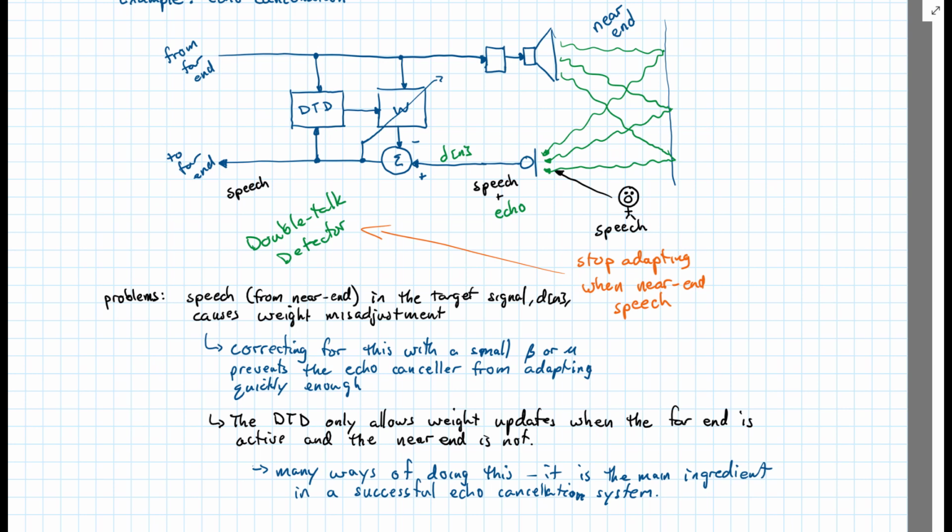So your filter is already starting to get longer, which of course slows down the adaptation. We can do frequency domain adaptation. There are various other schemes that can come into play, but regardless of how it's done, echo cancellation is a bit of a trick.